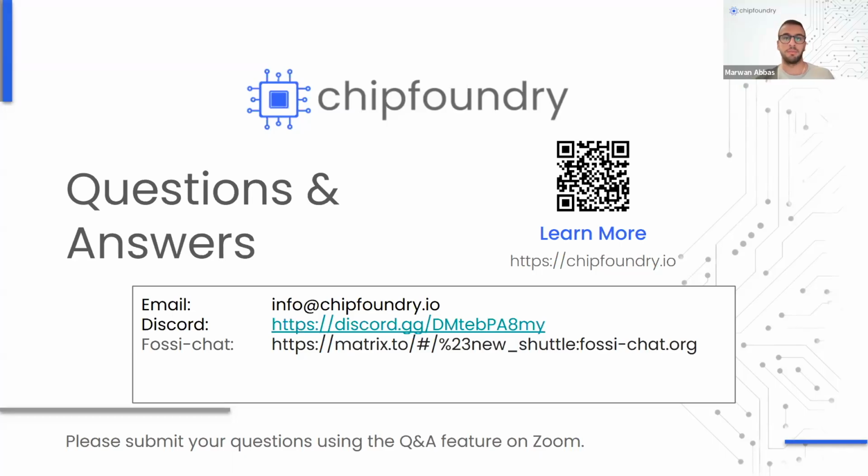And at boot, if a read request happens, is the data going to be random values, or is it initialized by something at boot? It depends. There can be two scenarios. ReRAM generally needs a first cycle of forming. When you buy it fresh from the foundry, it will be in a high resistance. ReRAM is just a tunable resistor, like a neuron.